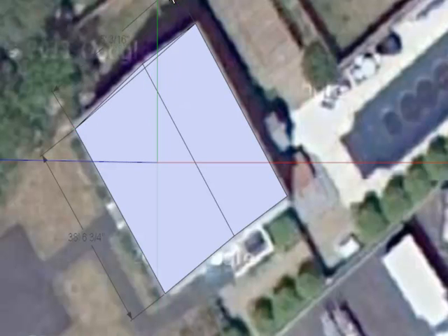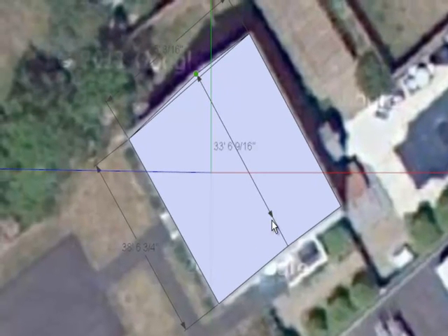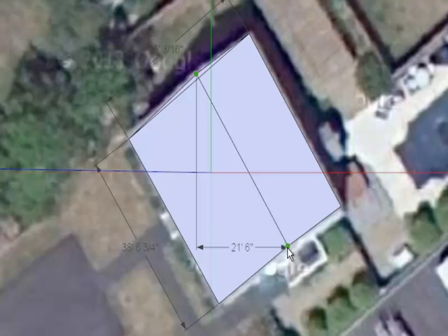I just get so excited with this stuff. It's just incredible. So you have the measurement there, like the ridge line. If you want to take the measurement for the ridge line, it's right there. You can actually take it right from here. One click to the click. It's right there, 39 11 and 9/16. You can do angles. But what I was trying to do is just get this to bring the number out. So it's 39 11. It's off by about a half an inch in 40 feet.